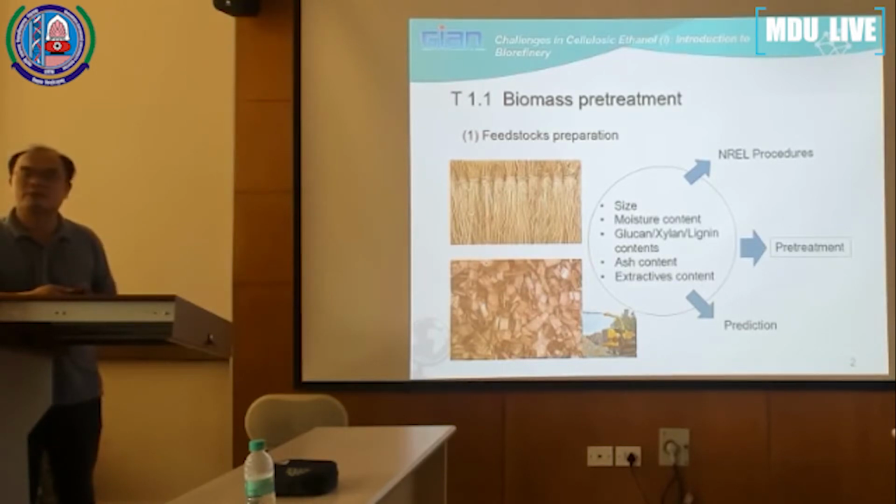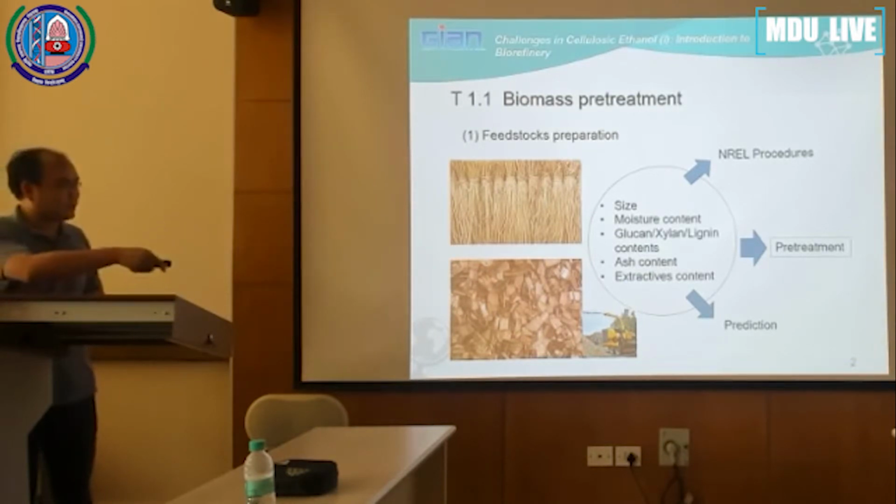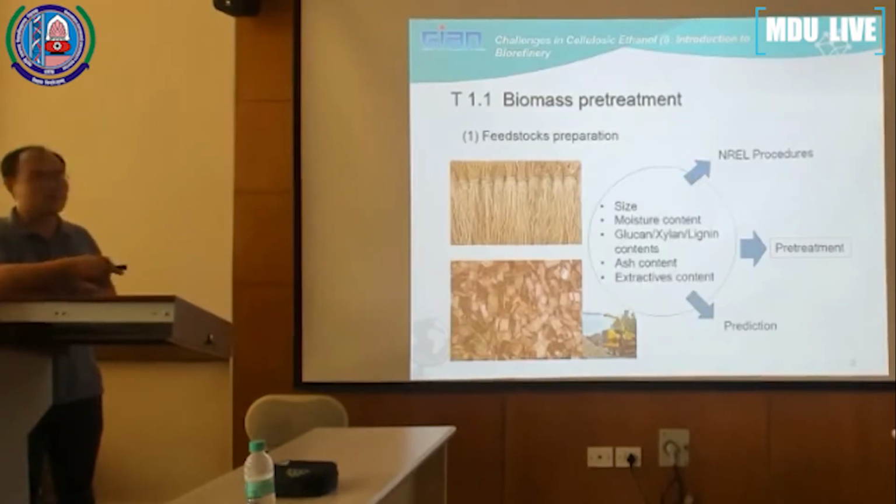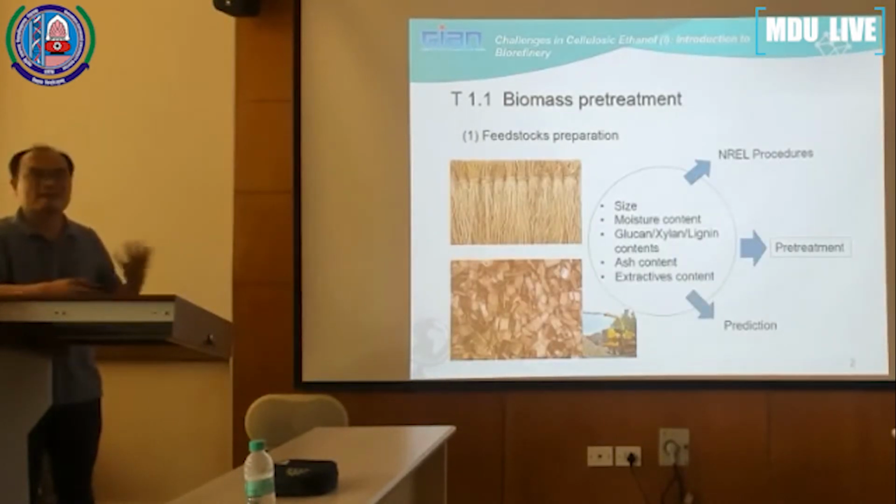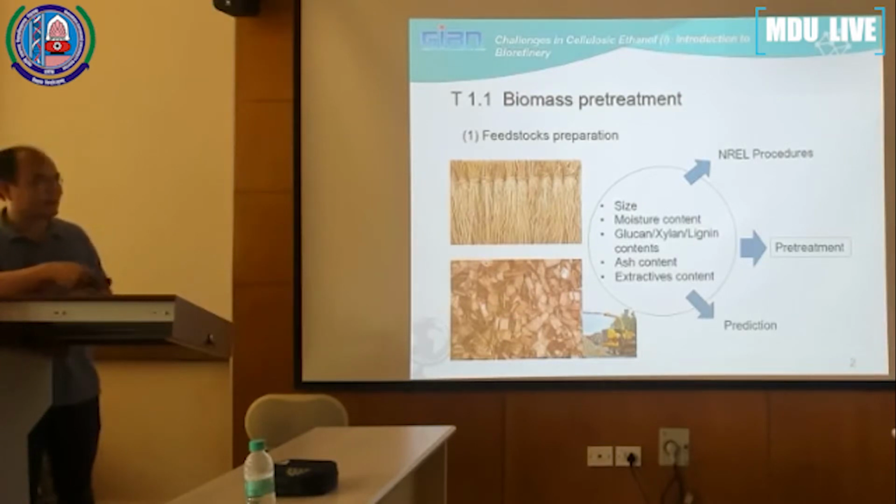The value is different. So how can we test it? We have a conveyor. It transfers the wood chips into the digester. During the transportation, we have some sensors to test the moisture. And the data is not stable, but we can calculate it, right? We can get the average moisture content.